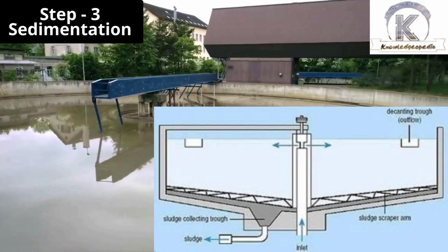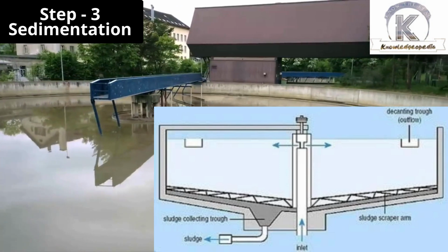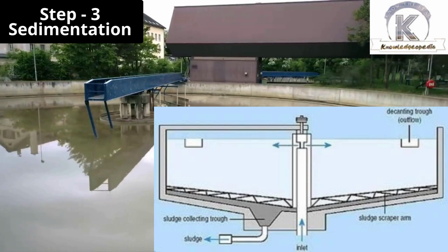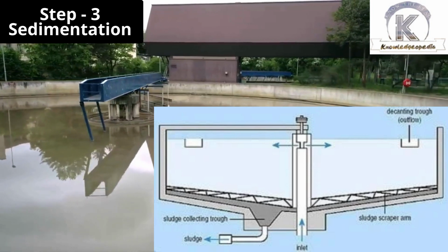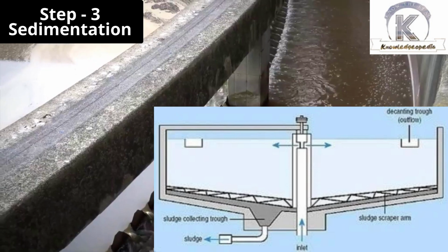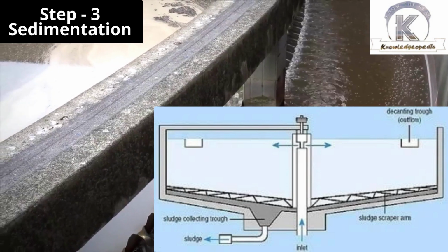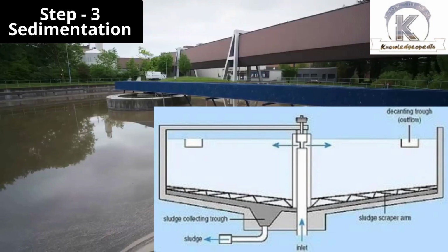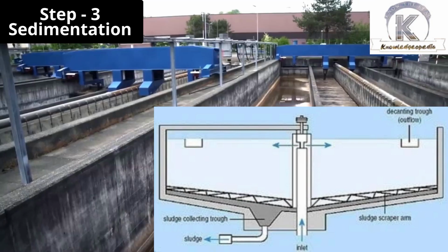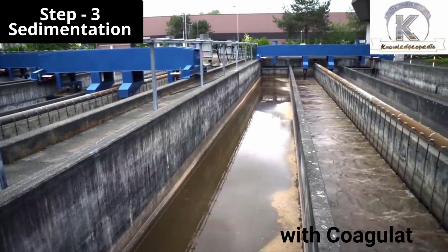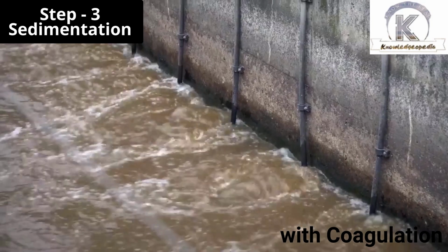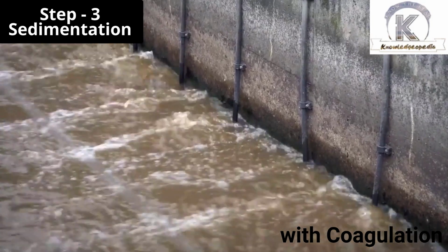We know that in stable water, bigger and heavier particles normally settle down and lighter particles keep floating. Similarly, in this process, water is slowly filled in a conical bottom tank through the middle pipes shown here. In a stable condition, large sinking particles settle down and are taken out through a drain pipe. The oily substances are wiped out from the water with the help of a flow-through channel wiper.